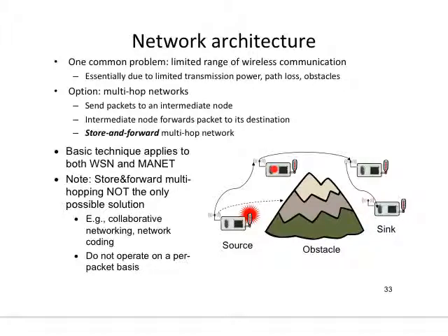And in fact, the power that you need to send from here to here is actually proportional to the distance to the exponent of alpha, d to the power alpha. Alpha here is what we call the path loss exponent.